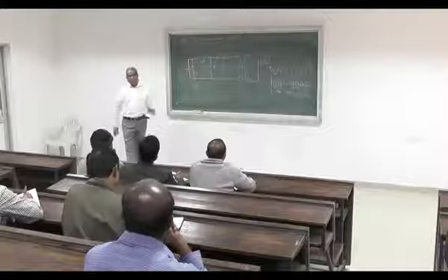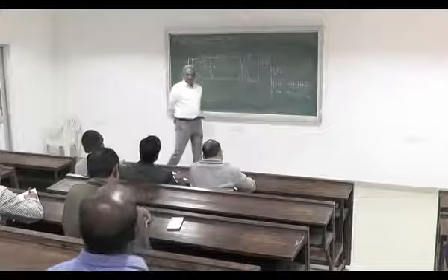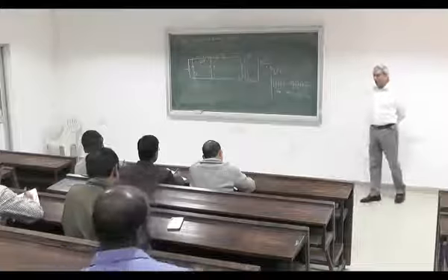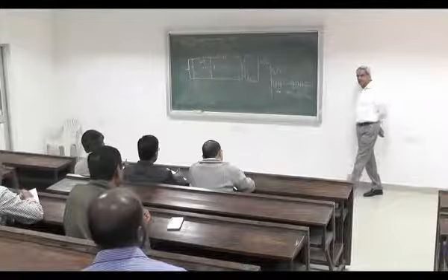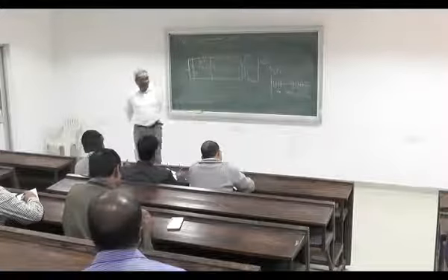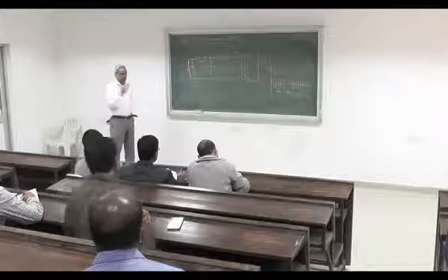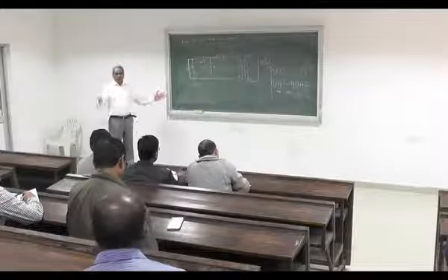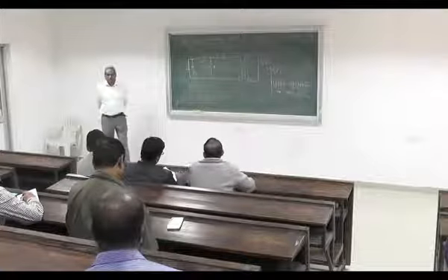You get the whole converter on for a number of pulses and the whole converter off for a number of pulses. When this converter is on, it's always operating closer to the resonant frequency, right? So you have 0 voltage switching, it's closer to the resonant frequency, you have the best power transfer, right? And now you are not looking at the small duration for the pulse width. You have a number of pulses, so you can modulate so that you don't have those time delay problems that you see in PWM.